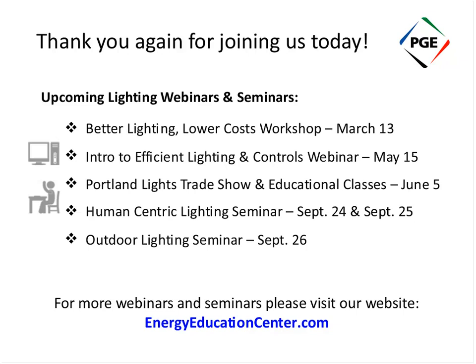I put some LED downlights in my home, on the other hand, and because I only have those on about 4 hours a day, it's going to take 6 to 7 years to pay that back. So those are, I'd say, hours of operation is going to be one of the key things that's going to determine your payback on LED lamp replacements.